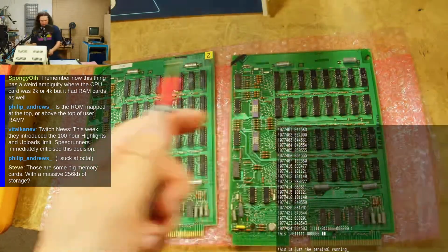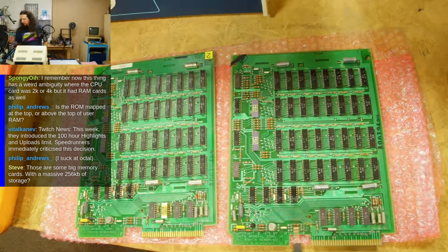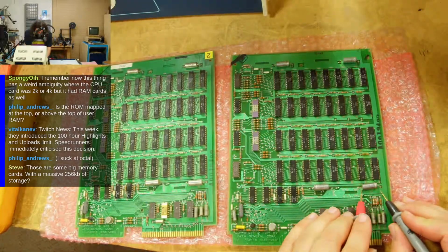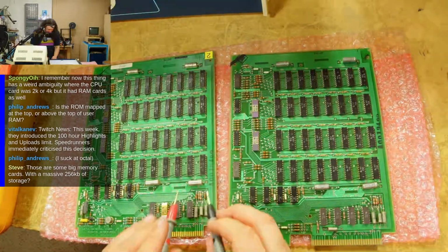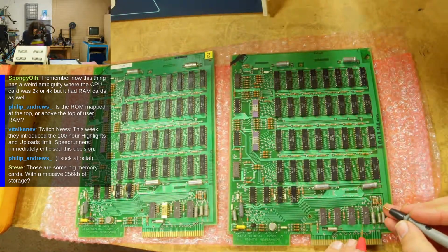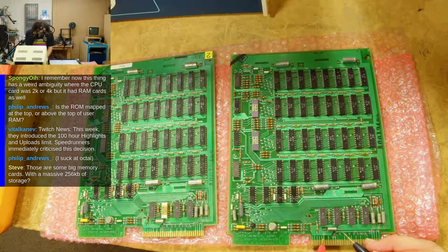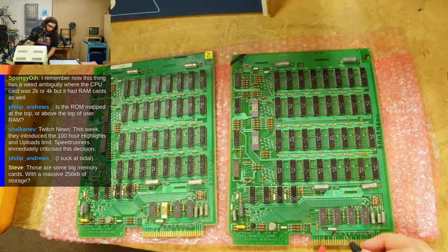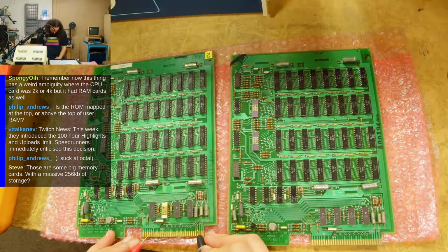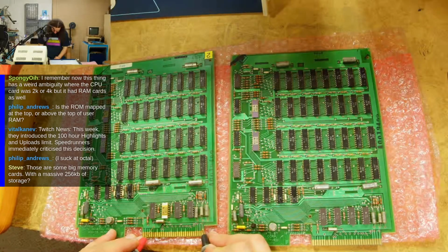Okay, so really quick here. I just want to hide the capture. I want to do a short test on this. So that's good. Is it like here and there? Nope, nothing shorted there. Just try here. There. All good. I'm going to do an actual resistance check between this. Now that should be 0. That is. And then this.